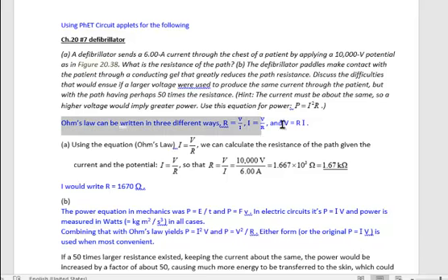So I wrote Ohm's law down here again. These are the three forms that it comes in. I only have one of them memorized, R equals V over I, resistance equals voltage over electric current, and the capital I stands for intensity of electric current. Then, of course, one algebra step, and you get the other two forms: current equals voltage over resistance, or voltage equals resistance times current. As I said, I only have one of them memorized, and I just use one algebra step to get to the others. Similar when I talk about the power law in a minute or so.